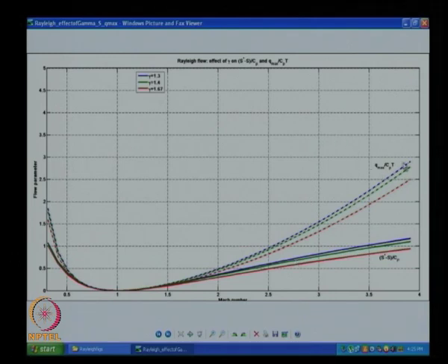Now we will go to the next one, Qmax. Qmax normalized by Cp times temperature. Let us assume we start with the same temperature for the whole flow field case which I have plotted here, any Mach number, same temperature I start with. If I pick such a case, I am finding that the subsonic case changes a lot. Qmax is high when I go far away from 1, much more than the supersonic case for the same amount. I will just go for say 0.5 and 1.5 if I look at it. Supersonic cannot handle as much heat as subsonic. That is the main point I wanted to say again.